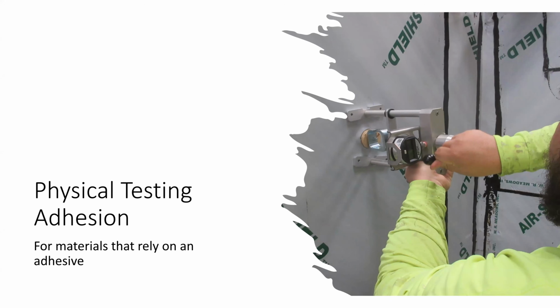Yeah, so if you do have moisture there, it does have that ability. If you are using concrete masonry units and a poured concrete, those two things will connect. They're typically never sealed. So what we've seen people do is put a little strip of a membrane where those two things intersect. That helps prevent water from ponding and getting into the exterior wall surface. So say a whole floor floods out, and hopefully it's not 2 feet, that would at least keep the water contained on the floor and not give it the ability to get onto the backside of that wall assembly.